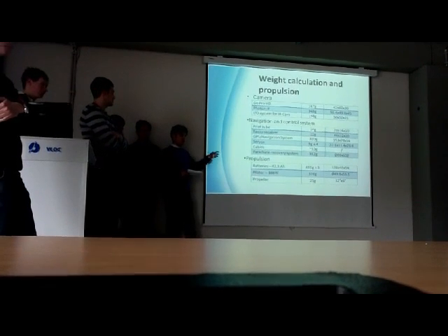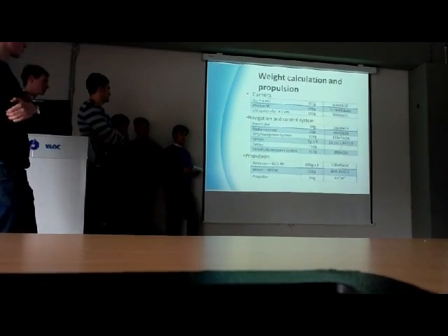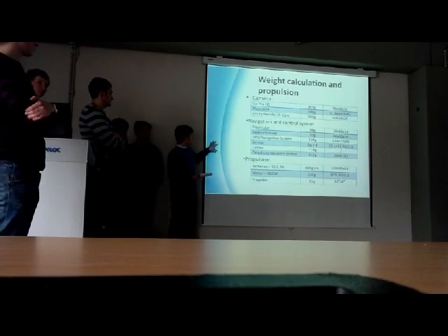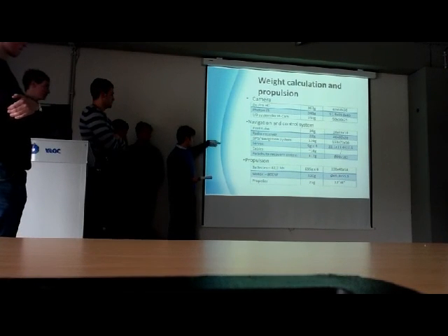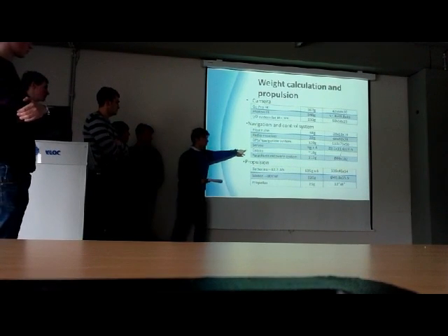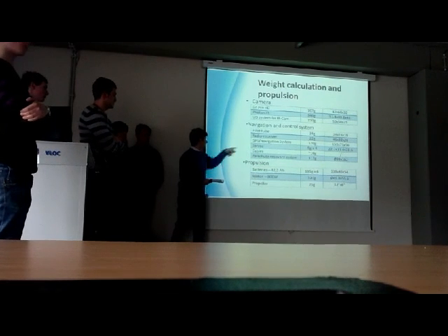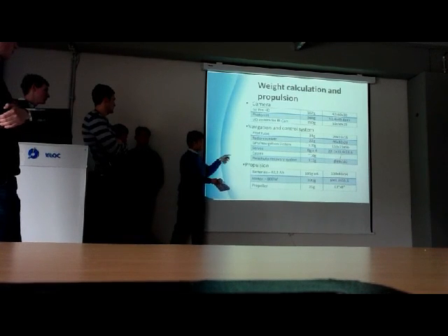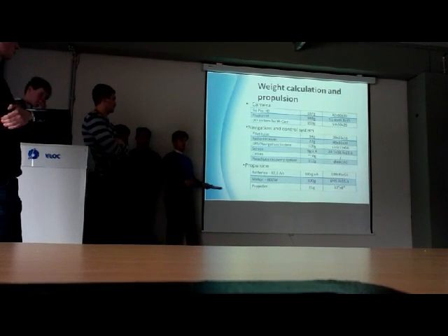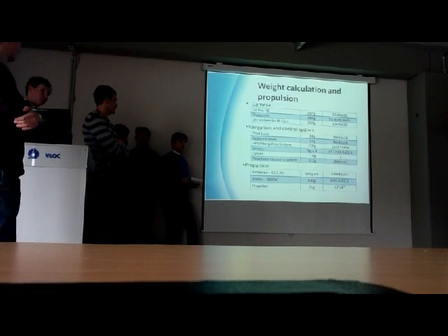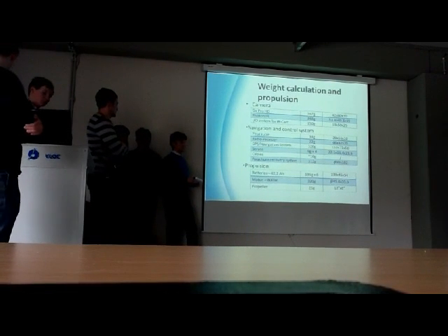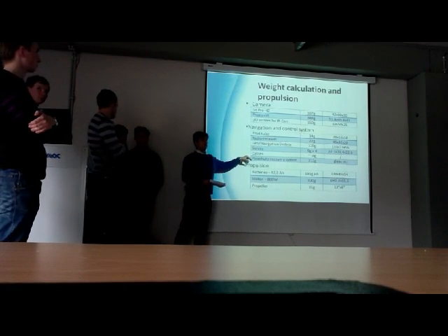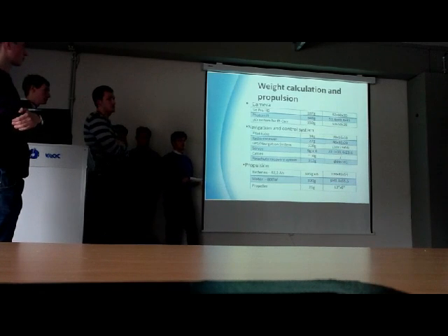Yes, this one we calculate. We make assumptions like mass. If the mass is here, its center of gravity is here, and another mass is there, its center of gravity is there, and we make resultants of the forces and find it in this way using a piece of paper, and more or less also assuming a constant thickness of the foil in order to approximate it.